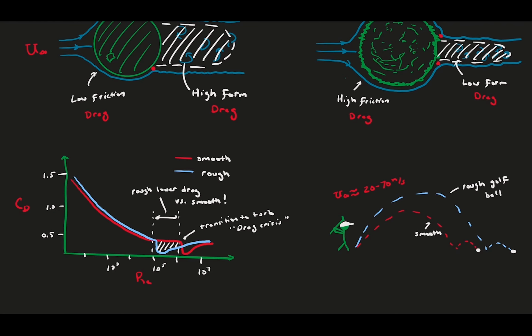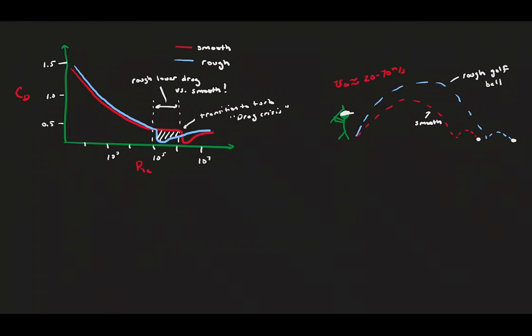These drag coefficient versus Reynolds number plots are common and are often also misunderstood, because on the face it looks like the drag force goes down with flow speed or Reynolds number. And that's not true at all. The drag coefficient is going down, but the Reynolds number and the flow velocity are increasing. This means the flow drag force is actually increasing with Reynolds number. It is only that the non-dimensional drag coefficient is getting lower.